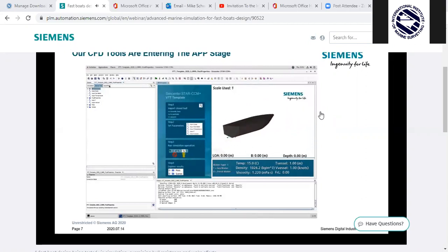And once we're ready, we can now go to our parameters. So we have a custom scene that only exposes the parameters that you need to input. In this case, this CAD model is built at model scale, but we want to analyze it at full scale. So we scaled it by our scale factor, which was 7. And now we have a 16-meter planing vessel, and we can change it from seawater to lake water by simply updating the water type.